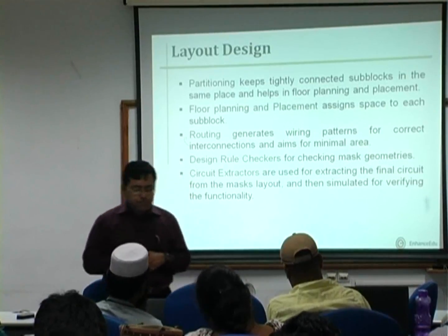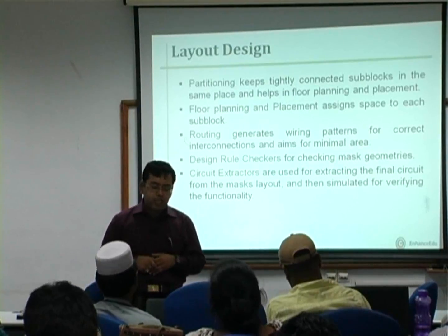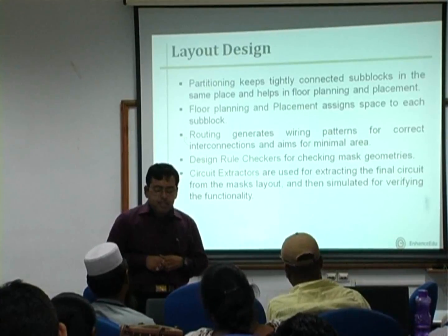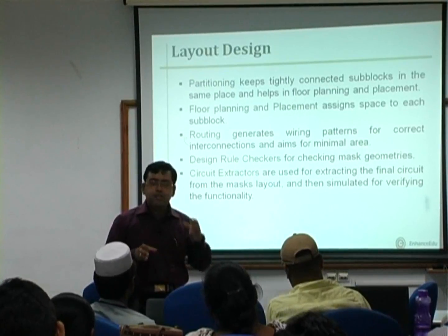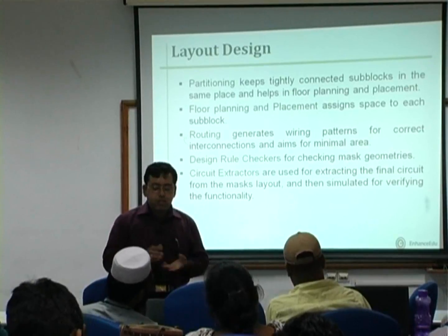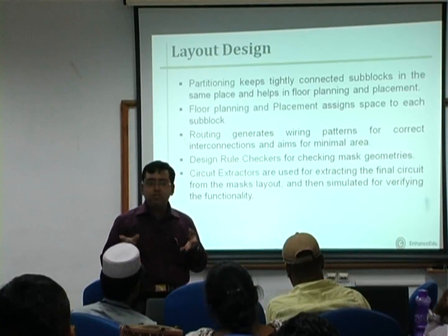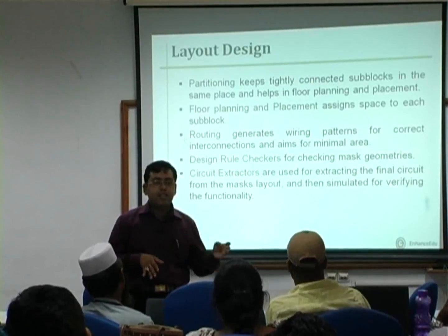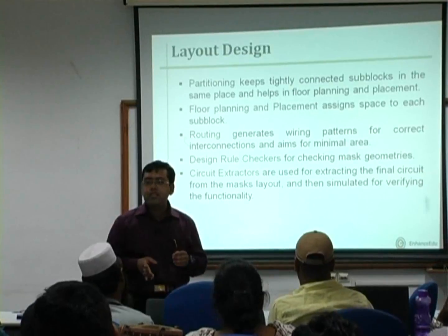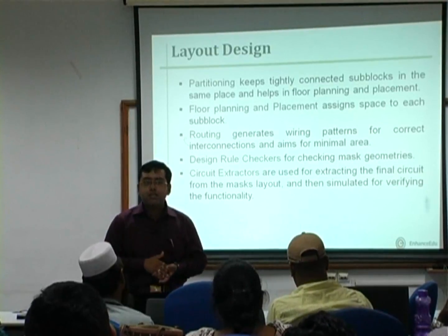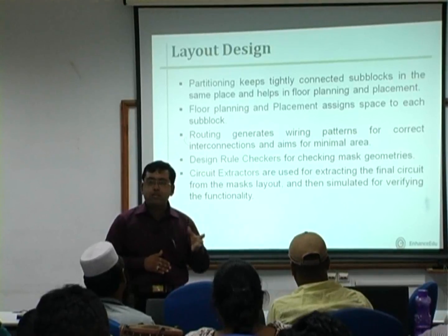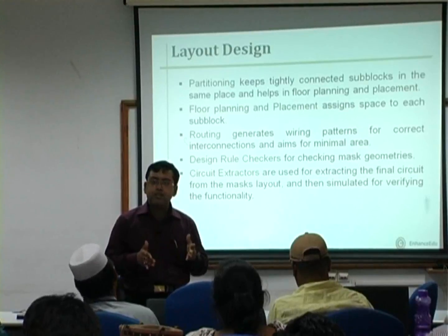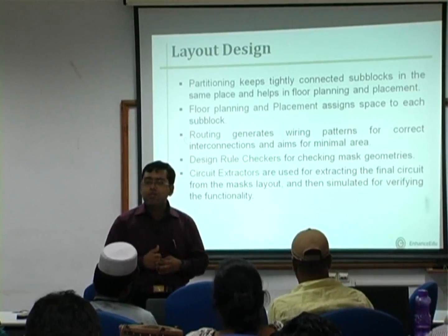And then you use design rule checkers, or DRC, for checking the mask geometries, and circuit extractors are used for extracting the final circuit from the mask layout, with the help of which you do the layout versus schematic verification. Almost all the CAD tools that come up nowadays have the facility to do layout versus schematic verification, to see whether the post layout simulation results agree within a certain limit with the schematic simulation results or not.